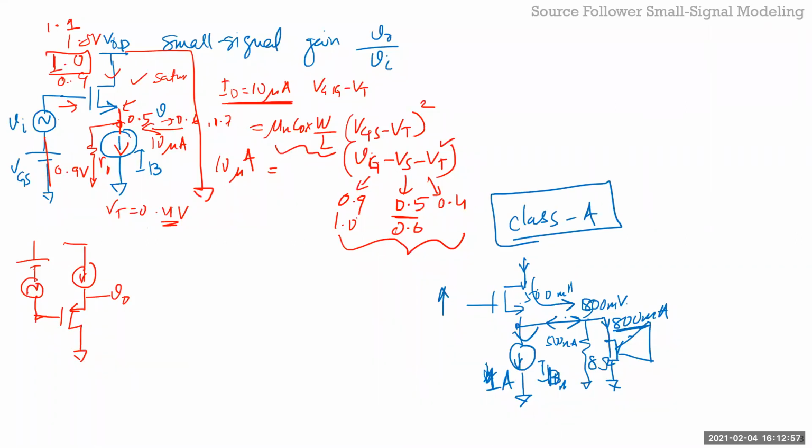Okay, so you can see if I want 1 amp, this is really not a good idea because no matter how much current you're providing to the speaker, you're always drawing 1 amp times VDD. Not a good idea, right? Because that's a huge power loss. So typically in big power amps, you want efficiency close to 100% basically. So efficiency close to 100% means you want this current to be basically zero. You don't want to draw any current here.